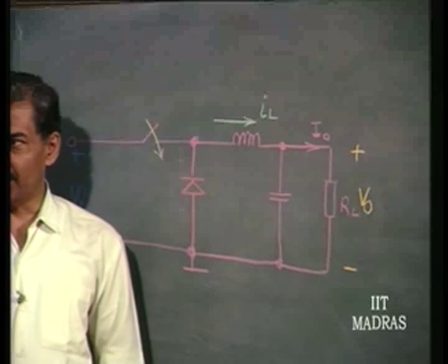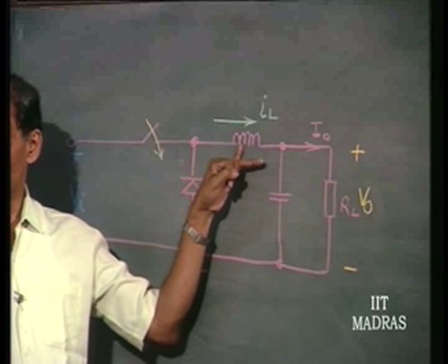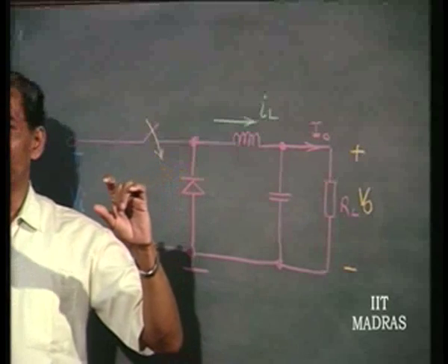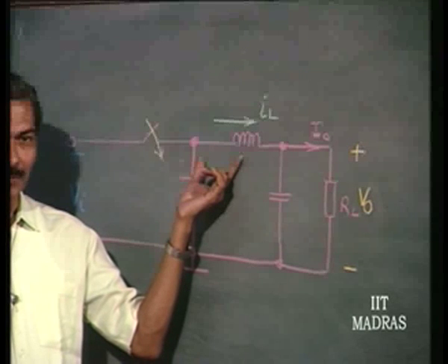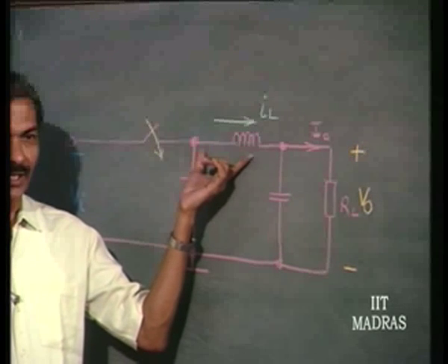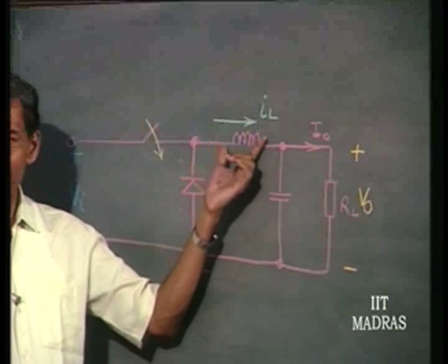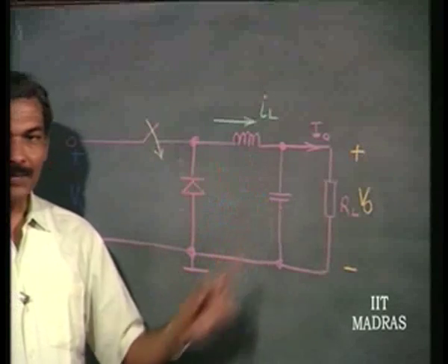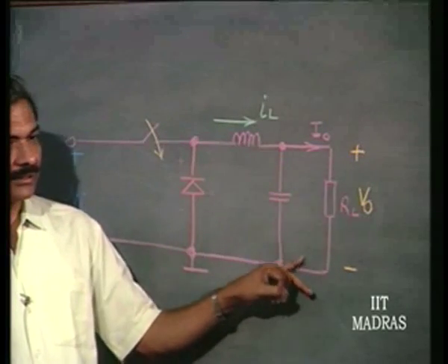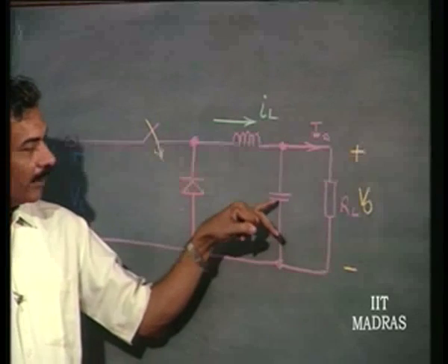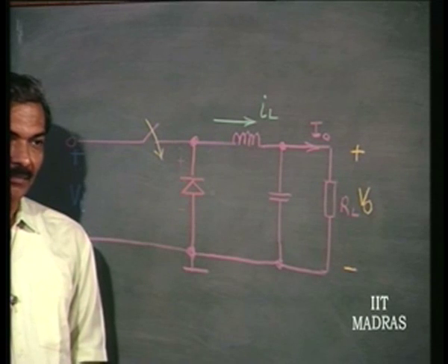One important point in the design of this is that the inductor has to be wound with thick wire because you want to make the resistance as small as possible. Simultaneously, of course, we have to also permit the load current to flow through the inductor. So, this is one part of the design, and the capacitor has to be a good capacitor. I mean, you might say, okay, the leakage resistance is going to be part of the load. No, there should be low series resistance associated with the capacitor.